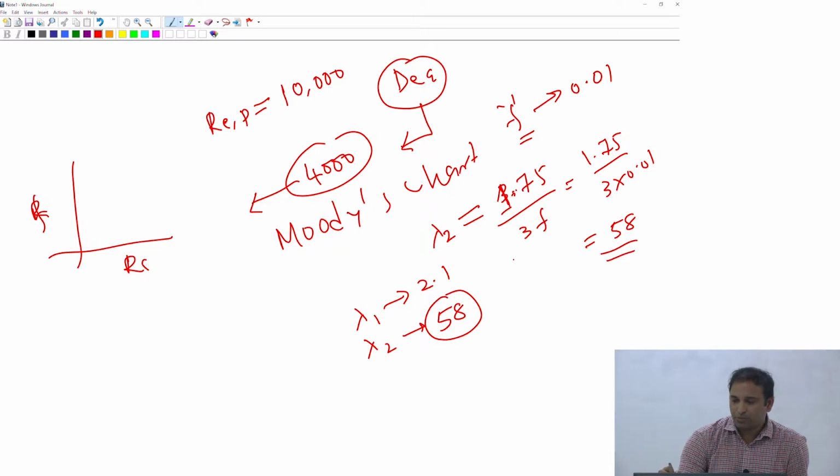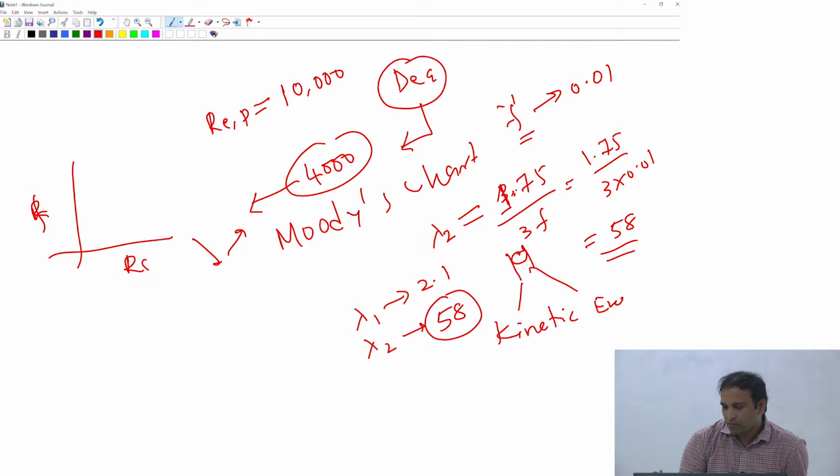In some channels the fluid flows in a channel of a particular area, and there could be expansion of the liquid at some locations, plus the liquid is going to turn the direction in which it is flowing. All that leads to much larger kinetic energy losses, and you can think about that in terms of a larger value of tortuosity. Yeah, go ahead.